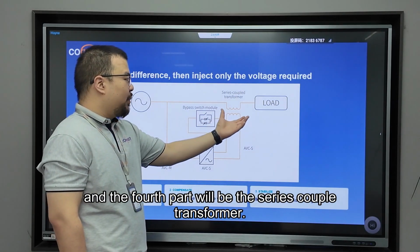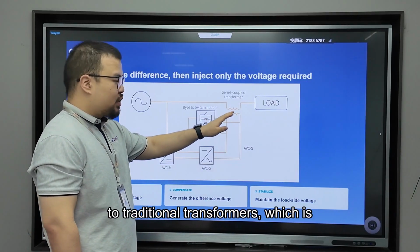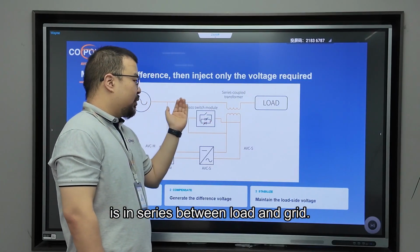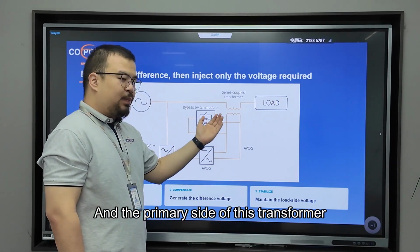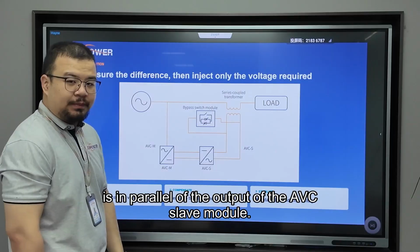And the fourth part is the series coupled transformer. This transformer is a little different from traditional transformers: the secondary side is in series between load and grid, and the primary side is in parallel with the output of the AVC slave modules.